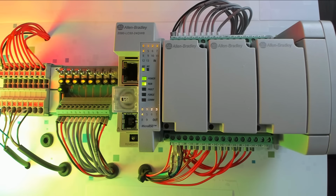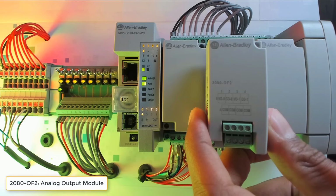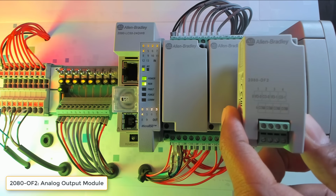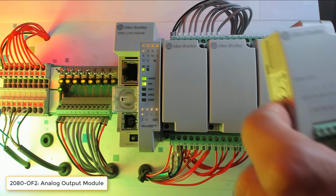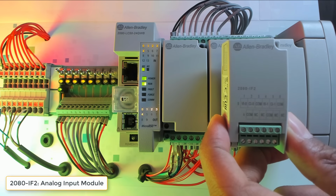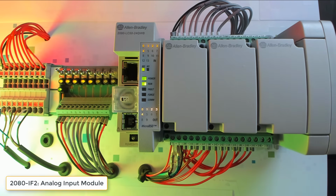So if you see the PLC again, here we have a plug-in module slot which I can connect here. I have two plug-in modules on my table. I will show you now. I have one of these plug-in modules which is 2080-OF2, which is an analog output module. I will connect this to the PLC once we do the analog output lessons. For that I can just take out one of these covers here and plug in this module. We will see that later. And then I have another module which is 2080-IF2. This module is an analog input module, so I can read analog inputs here.